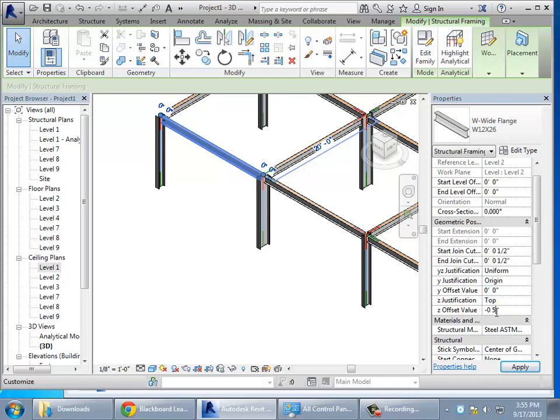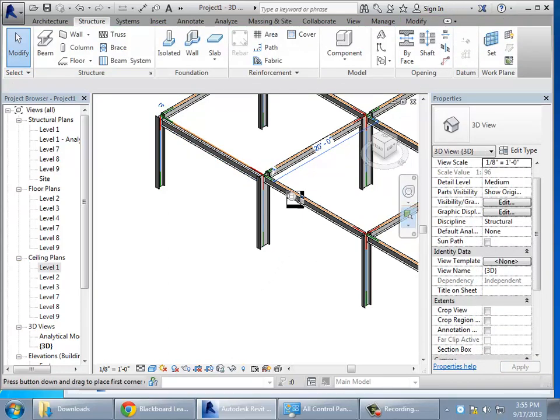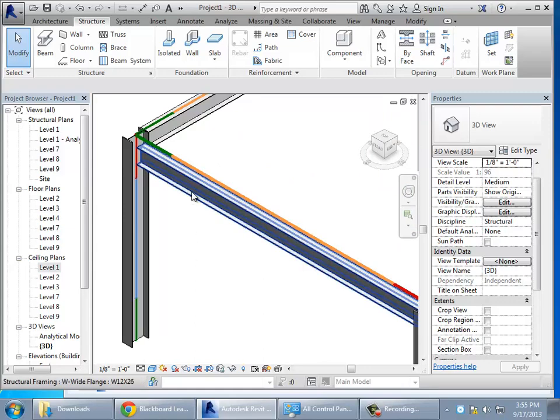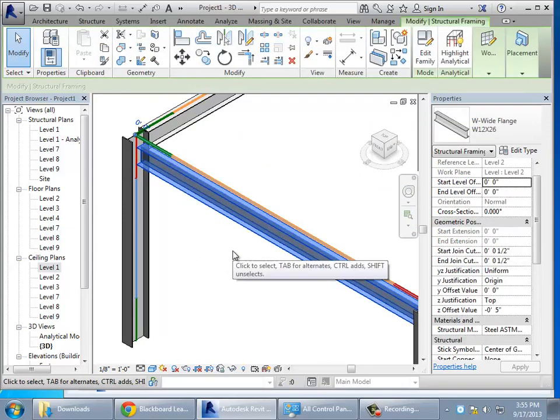Okay. Actually, this could be another instance where a reference plane could be useful. We were talking about that at the break, where you could set a reference plane 5 inches below and lock it to the reference plane. There are different ways of approaching that. But let me try just dropping that down 5 inches. What did I do that is so incredibly uninteresting but accurate? You drop that down 5 inches.